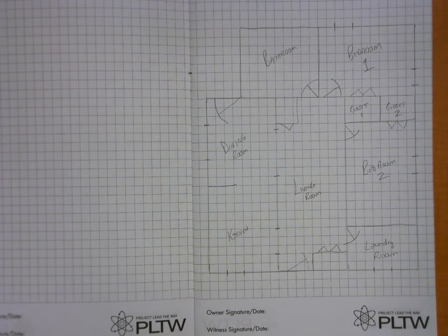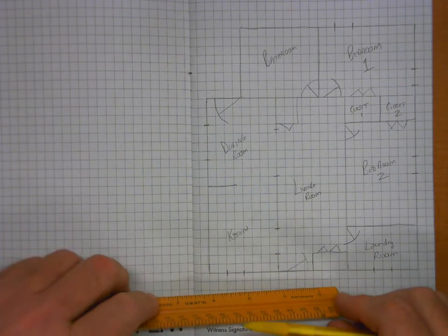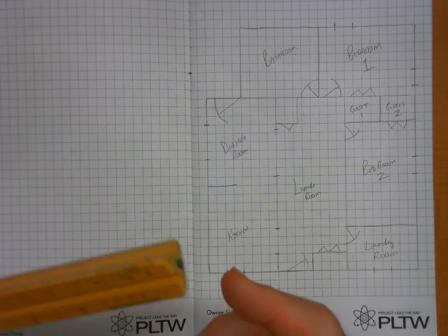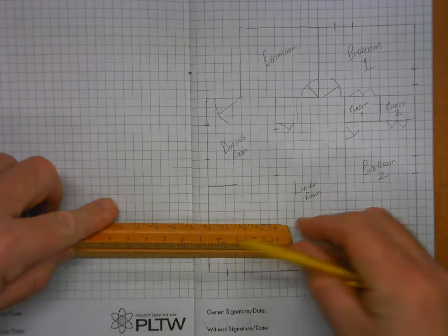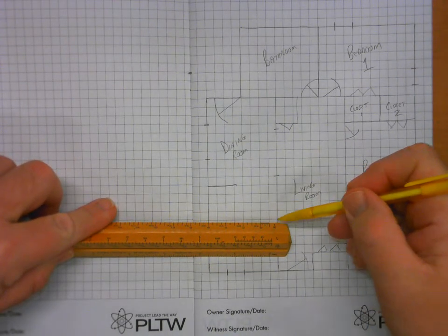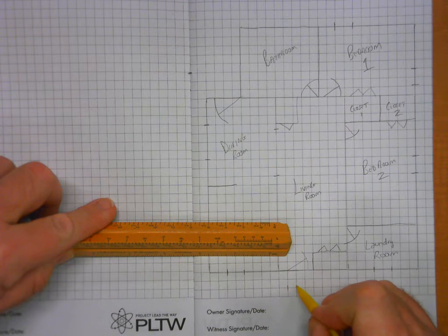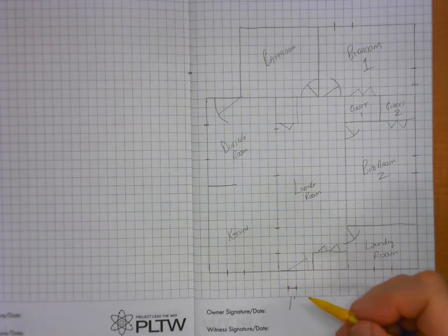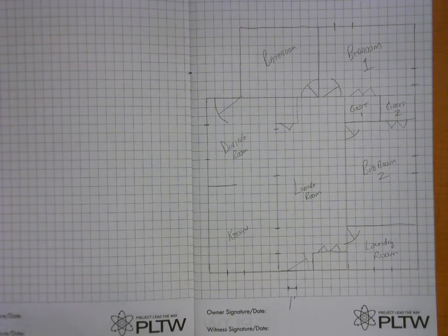So when I divided mine up, remember we could have openings between walls of 8 feet, all right? So if we look at this, what is each square? Let's find our 1/4 inch scale here. Each square, 1/4 inch equals 1 foot. So if you look at it this way, that is the same as 1 foot, okay? Each square is 1 foot. So that might help you if you want to have a 2.5 foot door opening, or if you want a 3 foot door opening, you can count squares.